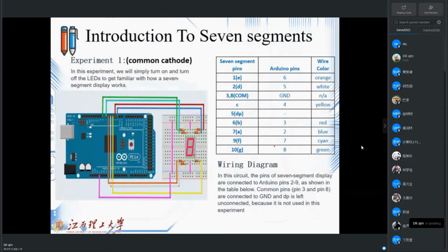Are these pins fixed when connecting to Arduino? Here you don't have any rule. You can change the pins on the Arduino side, but for the later job that I will tell you about today, where we should use the library for the 7 segment, you will have some limitations that you should see. The wiring diagram is what I show here, and you can see the wiring part is nothing but 7 LEDs. Let us see what the code could be.